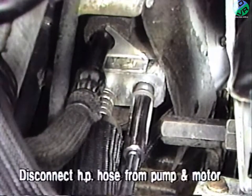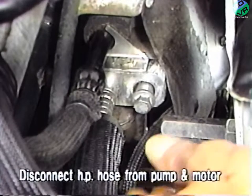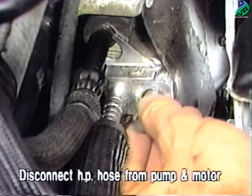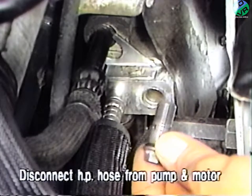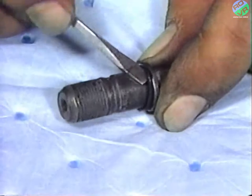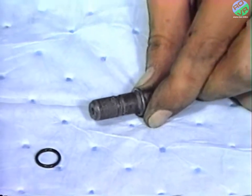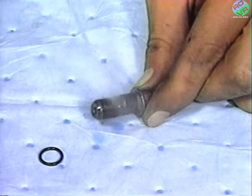First, on AC, AY, and AS body vehicles, disconnect the pump end of the high-pressure hose from the pump and motor assembly by removing and saving the banjo bolt. Remove the O-ring from the banjo bolt and clean the bolt.